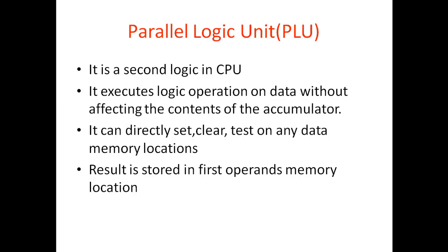Parallel logic unit. It is the second logic unit in the CPU. It executes logic operations on data without affecting the content of the accumulator. It can directly set, clear, and test any data memory location. The result is stored in the first operand's memory location.